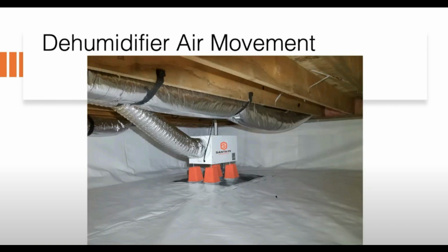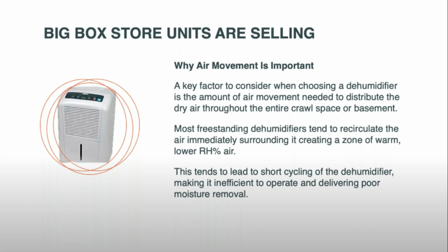As we talked about earlier, dehumidifiers are recommended to be located centrally in the crawl space, but that makes it harder to get to them and maintain them. By ducting them, we're able to locate them at a better access point and still get the better communication of drier air throughout the space. As we talked about before, the units that big box stores are selling are just not going to function as we need them to in a crawl space setting.